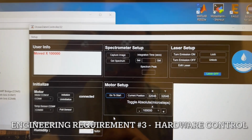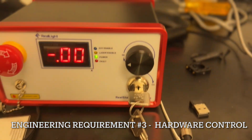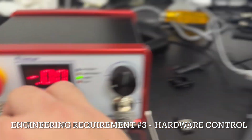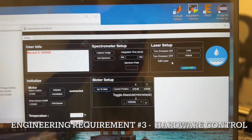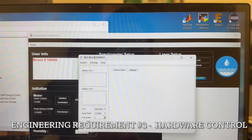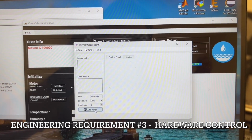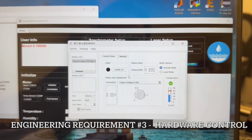The next software feature to show is the laser. So at the moment, it is turned off. As you can tell, when I do this, this is where the emission comes out. There's no laser here. But when I go to edit laser, and I hit this button, the laser controller should come up. There it is. I'm going to change this port to COM5, the baud rate to 9600. This corresponds to the laser itself. I'm going to hit add device, and here you can see an interface for the laser.